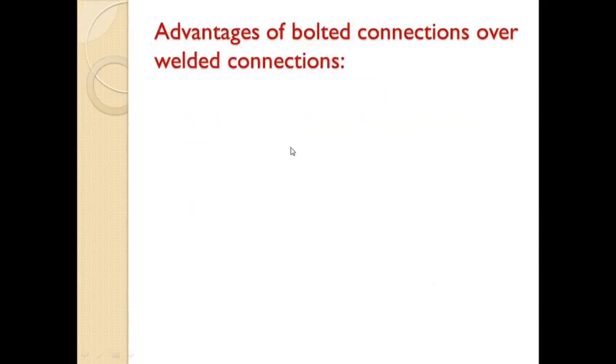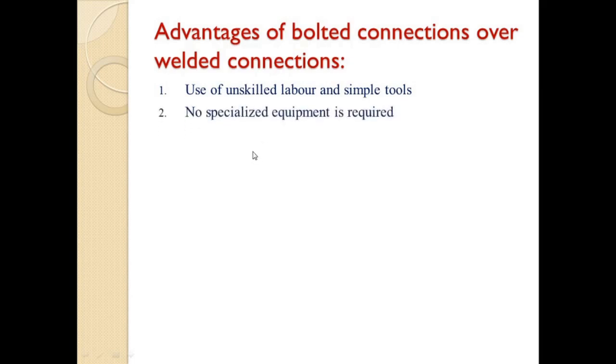So let us see the advantages of bolted connection over welded connection. First, we require unskilled labor and simple tools for bolted connection. In case of welded connection, we require skilled labor for welding and also complex tools. Second, no specialized equipment is required. Like in welded connection, we require safety glasses, helmets, and gloves. Such equipment is not required in case of bolted connections.